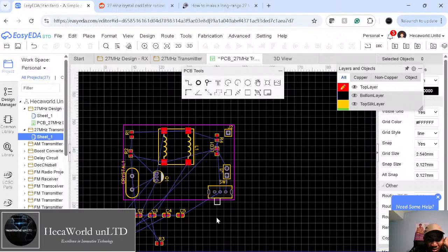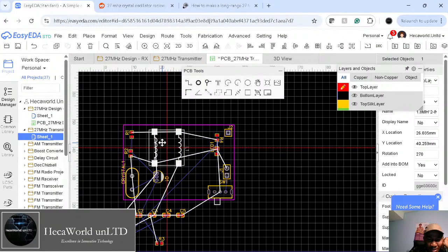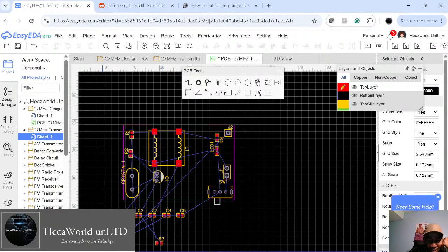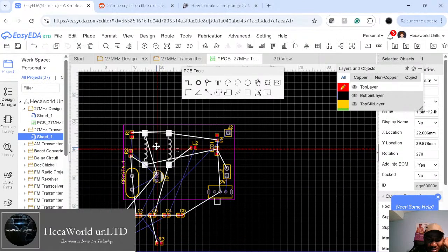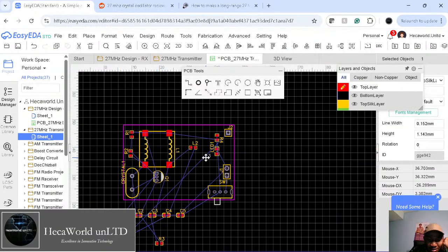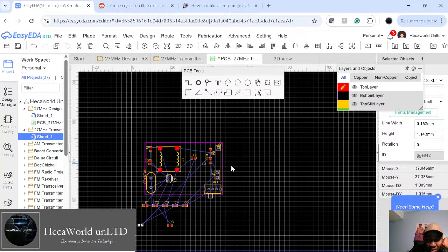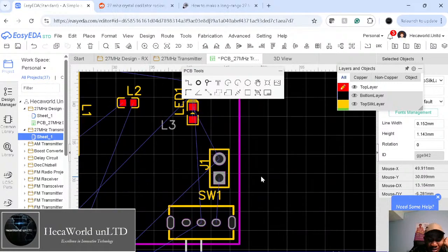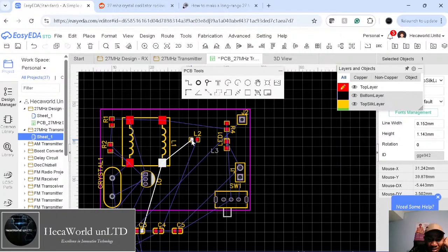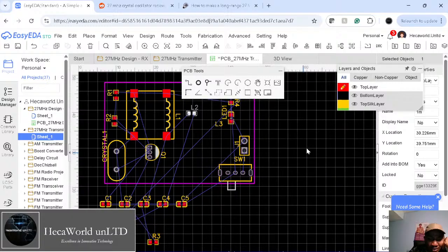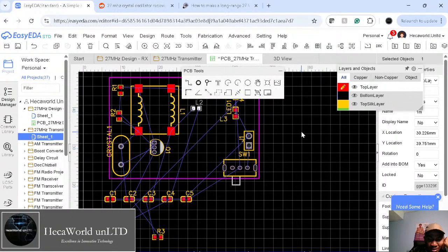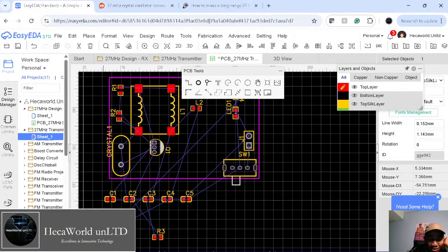And then the other components we need, inductors L1, L2 and L3. They're gonna be here. This L1 is too big, it's ginormous, but we're not gonna worry about that for now. If you select the wrong component, you can just do Control Z to undo. So let's just move this. The L3 needs to come in. Where is the label? Should be close to it.